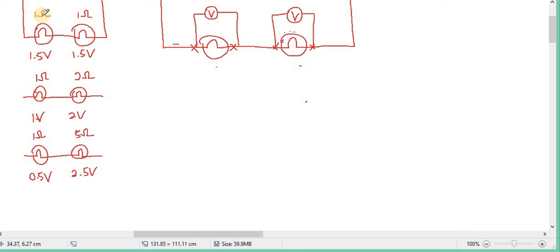You see, this ratio is 1 to 1, right or not? So the voltage also 1 to 1. You see this one 1 to 2, so the voltage also 1 to 2. This one 1 to 5, also 1 to 5. You see or not? Okay? So again, the higher the resistance, the more voltage it will get. Why? Very logical.